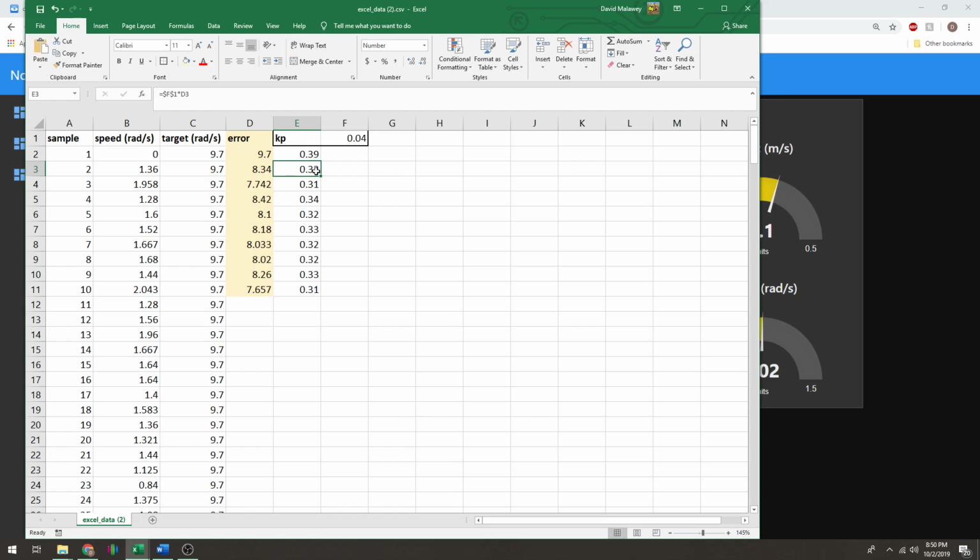So 0.33 is going to be the full control effort. In this case, we call that UP, or U sub P. And U sub P is going to be 0.33, and that will also equal U total, since we're not using integral or derivative control. Then this 0.33 will mean that 33 out of 100, basically 33% of the time, our signal to the motor driver will be high, and the remainder of the time the signal will be low.